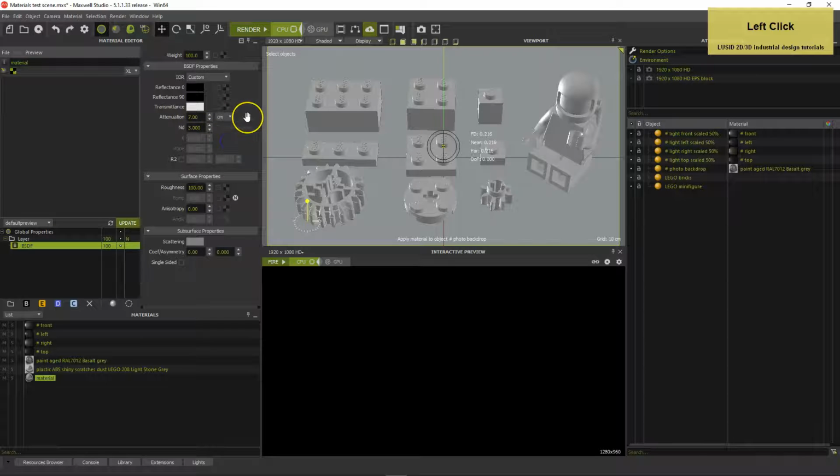The attenuation distance determines how far light travels through an object before losing half its energy, which also influences the transmittance color's visibility. Set the roughness to 1 and the refractive index ND to 1.581 and keep the extinction coefficient K at 0. Activate Force Fresnel to maintain bright reflections for all viewing angles.